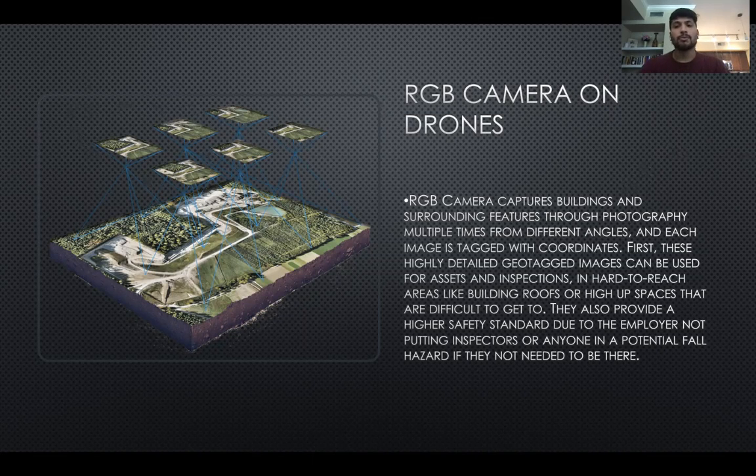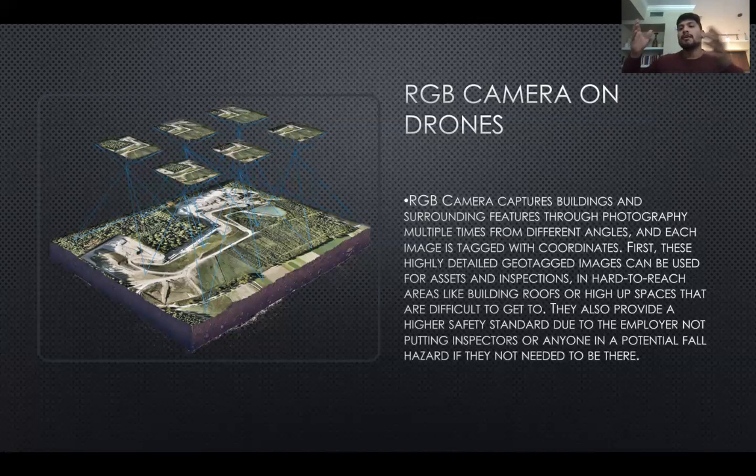That goes back to what I was saying when we first started this video, is that through drones you're able to get into, like, let's say you want someone to go into an elevator shaft but you don't really know what's wrong. You could put a drone in there, have it fly up, and figure out what needs to be fixed first before you even send someone up there. It also helps inspections. Same situation. If an inspector is okay with it, you're able to use a drone to go up an elevator shaft, check out all the CMU block, check out everything that needs to be there, make sure it's in place, and that way the inspector isn't putting himself in danger from a potential fall hazard.